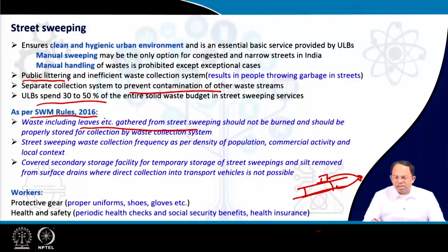So if he feels that's not a good option, then instead I will work here and I will have a storage container over here, where as soon as my vehicle or whatever container I am using gets filled, I will store my waste over there, and then keep on storing this waste in the containers. Later on, a vehicle will come at a certain time and pick up this waste from all these containers and take it for disposal or to some treatment facility. So both the models are fine. Depending on the context, the kind of street, and the amount of waste, we have to design which is the better system for this particular area.